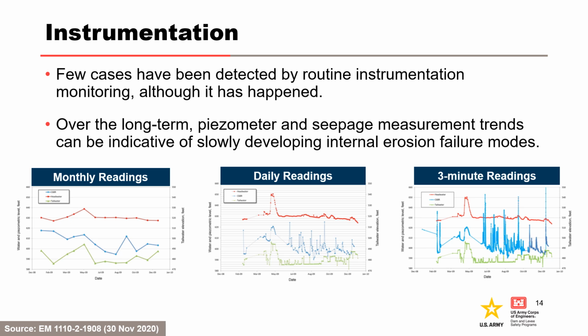Daily readings should typically be performed during a modification project if instrumentations are read manually, for limited periods of time during high water events, or for noted unusual instrument readings requiring further investigation. Automatic data acquisition systems, or ADAS, make possible a much higher instrumentation reading frequency than is practical for manual reading.